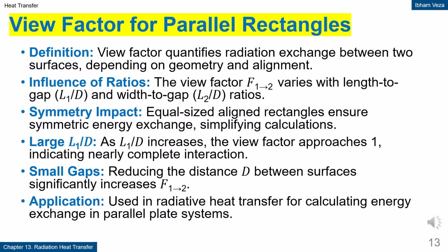View factor for parallel rectangles. The view factor between two parallel rectangles is strongly influenced by the ratios of dimensions to the separation distance. If both plates have equal size and are symmetrically arranged, the energy exchange becomes symmetric. When the length to gap ratio is very large, the view factor approaches 1. This means almost all radiation from one plate reaches the other. A smaller gap significantly increases the radiative interaction.